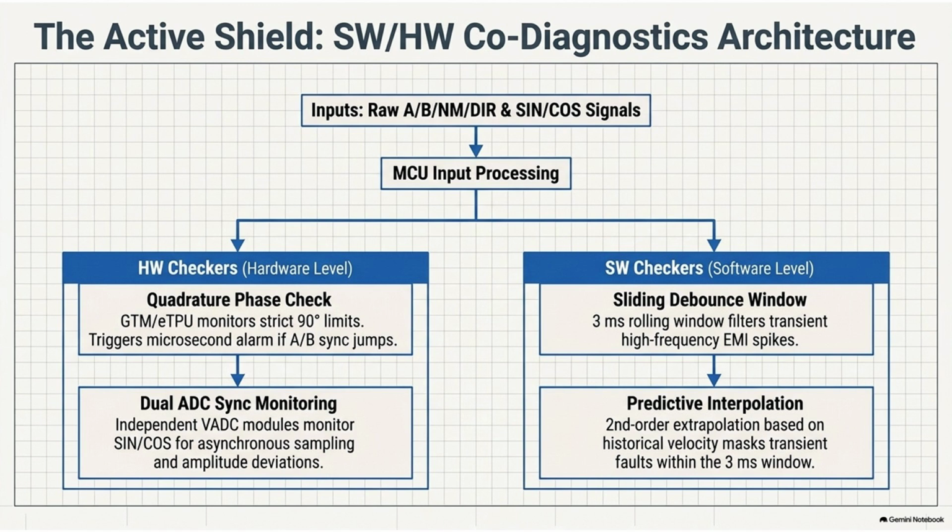Okay, so you have the main core, the doer. It runs the highly optimized, dynamic, field-oriented control loop, spinning the motor based directly on the encoder's data. Right. But the secondary core, the checker, completely ignores the encoder. Instead, it looks at the raw electrical current and voltage being fed into the motor's stator. It runs a complex mathematical model called a Model Reference Adaptive System, or MRAS.